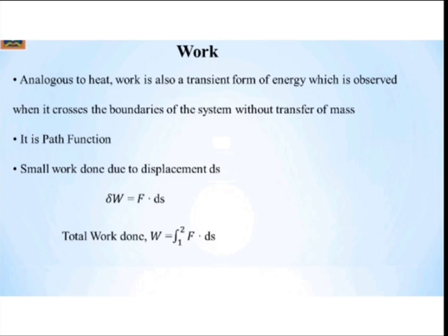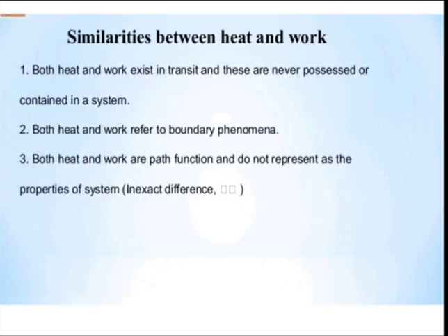Then similarities between heat and work. Obviously both are forms of energy. Both heat and work exist in transit, and are never possessed or contained in a system. Both are referred to as boundary phenomena. Both heat and work are path functions and do not represent properties of the system.